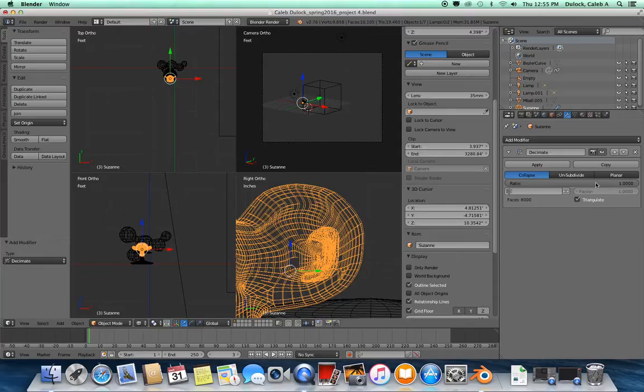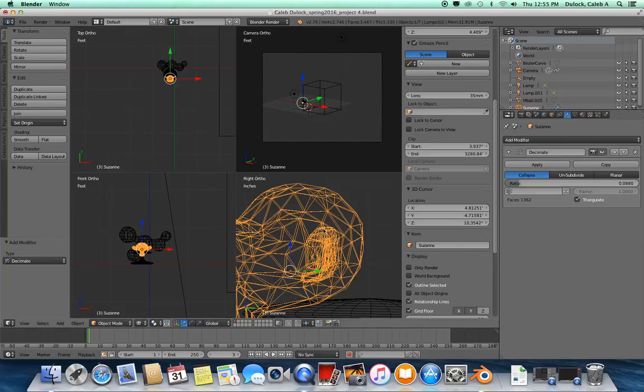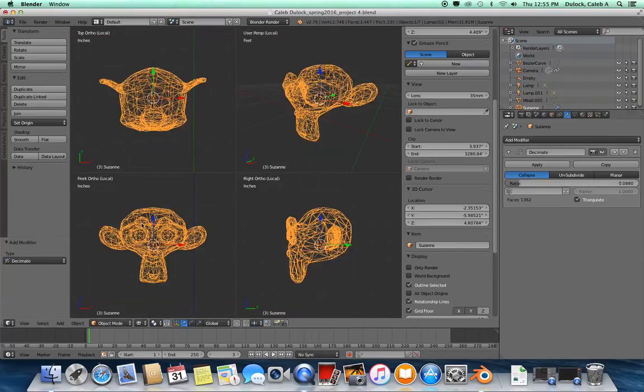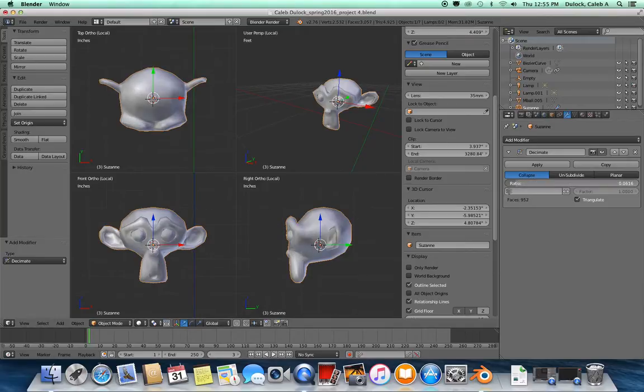It's going to collapse polygons together or merge them as I reduce this. So you can see my model here too. You can also watch as that number changes, as I take the ratio down, the object's surface quickly gets simplified more and more as I go. You can see it very well in this view. We can also switch our shader back to solid. And here in a second, you're going to start seeing it change in the physical model. You'll start to see quality get reduced.